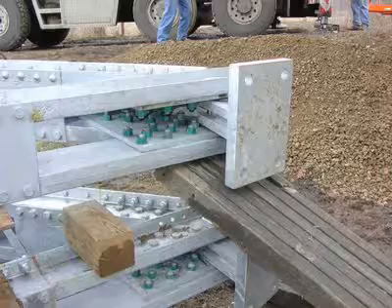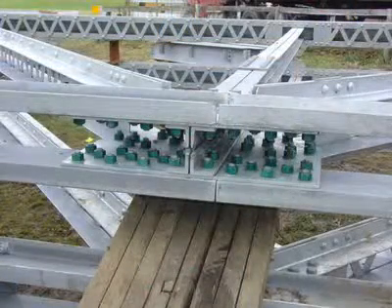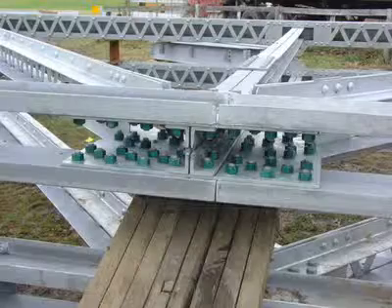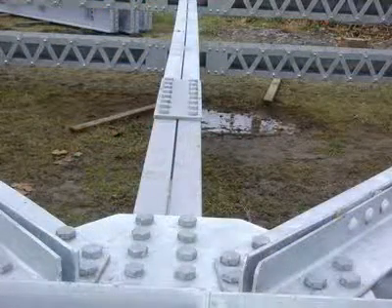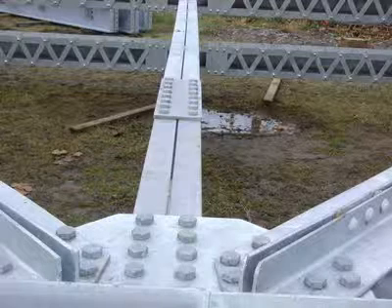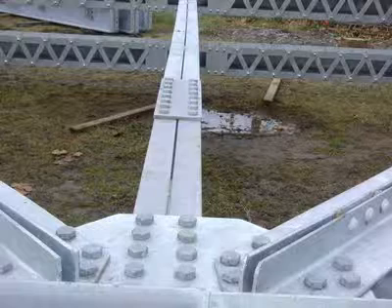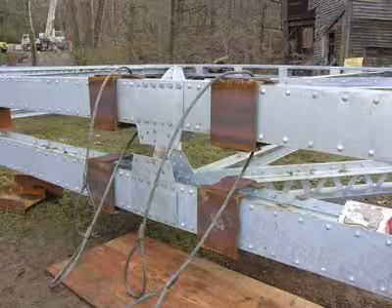A325 bolts, new bearings, new gusset plates. There was some of the new bottom chord replaced here. Of course, these gusset plates were replaced. The rivets that were secure were left in. The verticals had a lot of rust, so they were cut off about 6 feet above the bottom chord, and new sections were spliced in. Everything bolted back together. The unit was taken back to the site, laid on the ground, bolted, assembled in one piece.